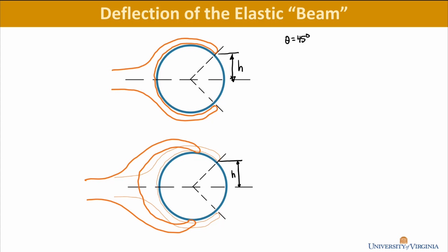So here's h on that drawing, it's still there. And the maximum that the prongs of this snap fit part need to extend to would be the diameter of the rod, d, divided by 2, or the radius of it. So the deflection is just the difference between these two: the diameter of the rod divided by 2 minus h, which is how far the snap fit part extends.